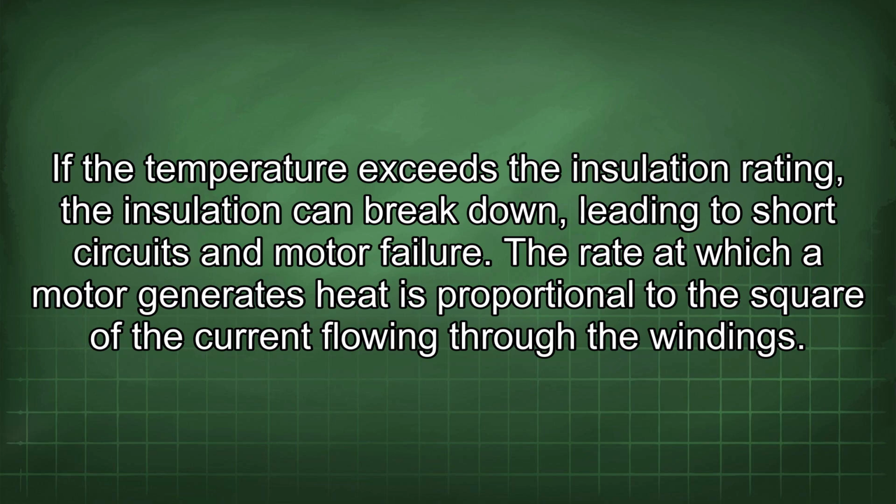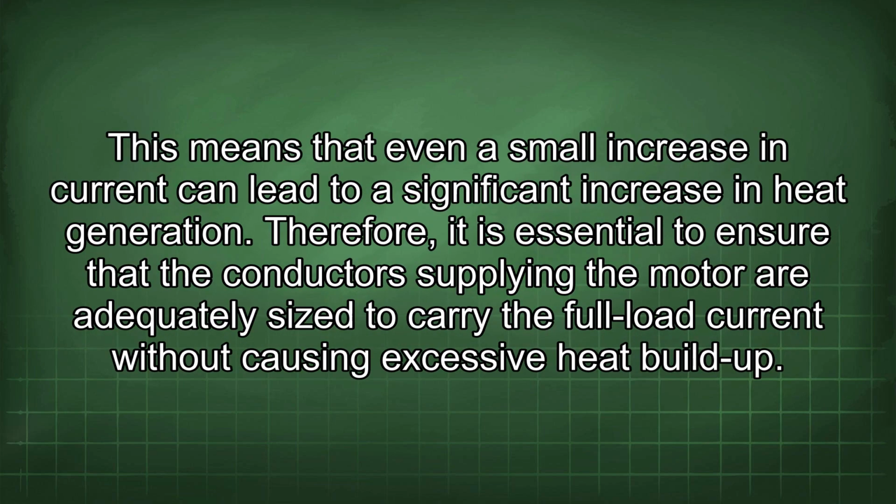If the temperature exceeds the insulation rating, the insulation can break down, leading to short circuits and motor failure. The rate at which a motor generates heat is proportional to the square of the current flowing through the windings. This means that even a small increase in current can lead to a significant increase in heat generation. Therefore, it is essential to ensure that the conductors supplying the motor are adequately sized to carry the full load current without causing excessive heat build-up.